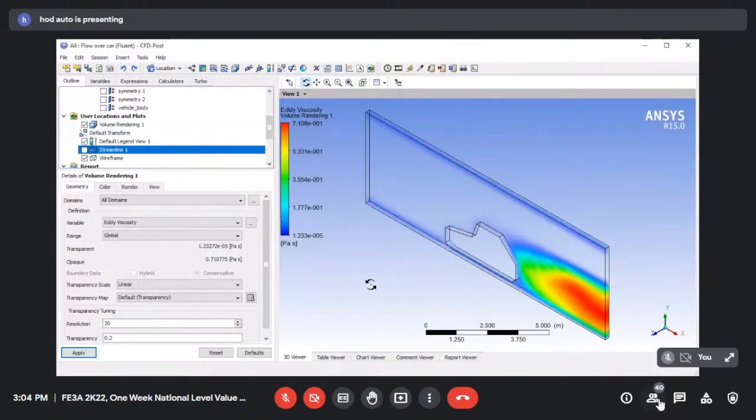I can see it is showing the regions of turbulence at the end of your car. That's the region of negative pressures. That's the region of your wake. That is your von Karman street, where low pressure regions are being created. I'm just giving it 50-55 kilometers per hour, and when you try to iterate at higher speeds, at one particular point your solver says turbulent viscosity has increased more than 5,000, and hence you have to use a different solver to do it.